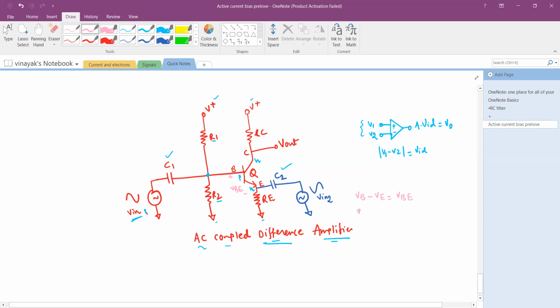Assuming that at the signal frequencies of interest, the capacitors we choose have a very large value, large enough that they act as an AC short, our input gets coupled to the respective pins.